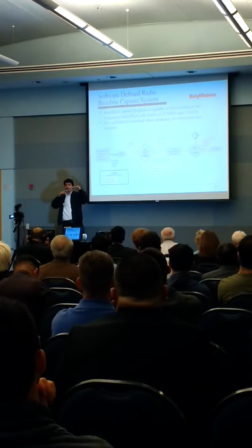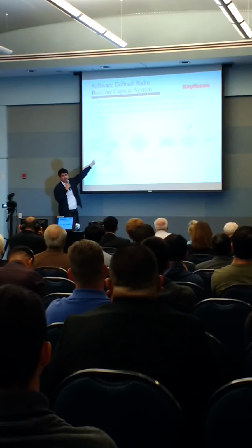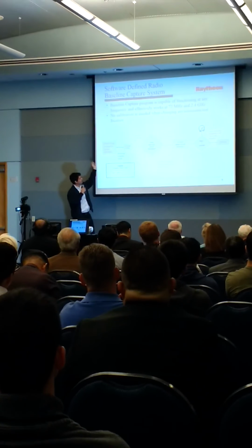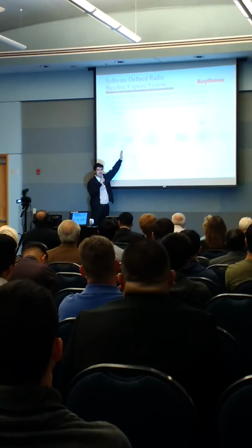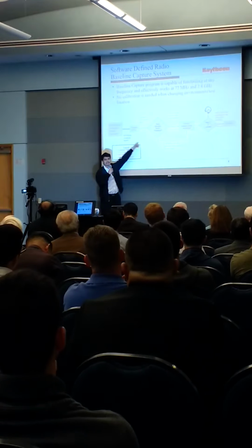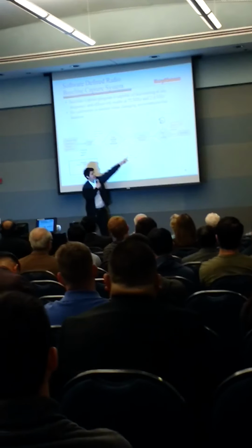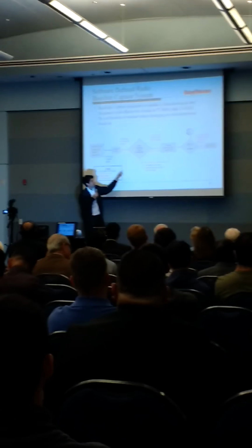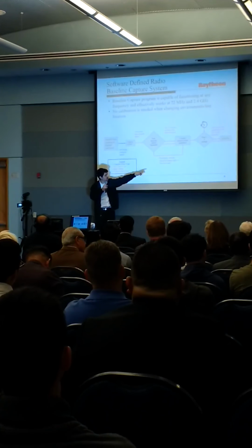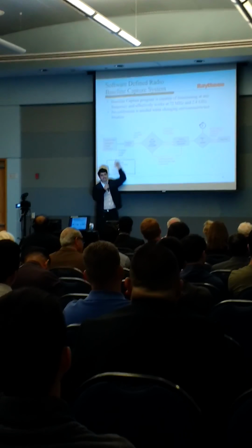So we just look for the higher amplitudes. So here's our HackRF1 source, the digitizer. It sends our digitized data. We convert it to time domain. We pass it through a threshold initially set to 0, and then we store it in a variable. That amplitude becomes our new threshold, and we continuously do it.